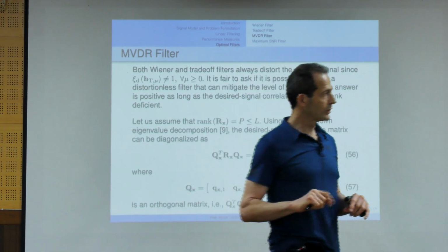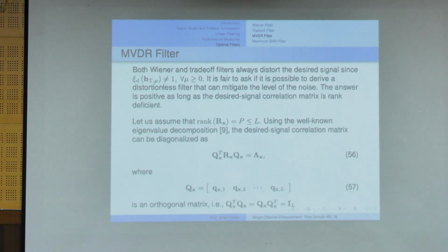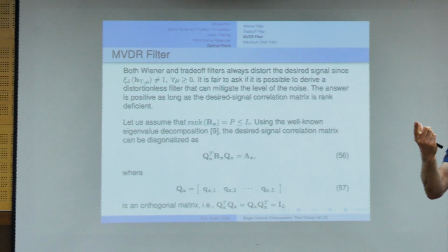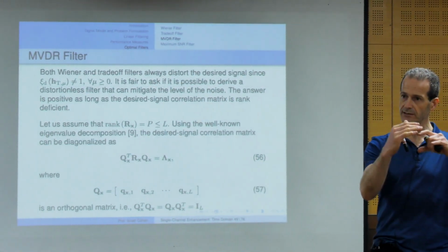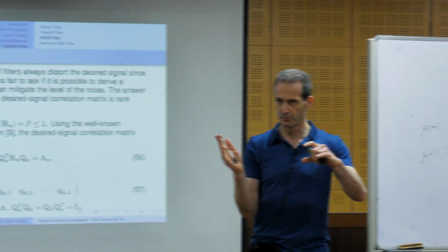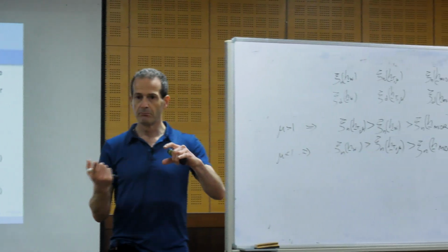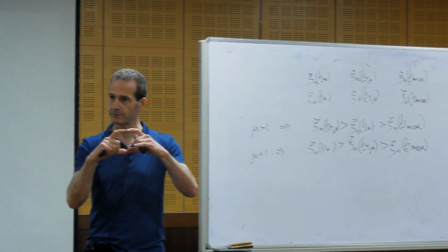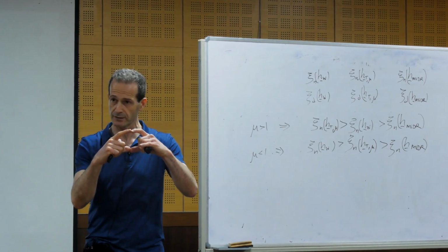Okay. So if we compare it to the Wiener filter, of course, it will remove all the noise in the noise subspace up to 1 kilohertz, and above 2 kilohertz, just like the MVDR. But what will it do in the signal subspace from 1 to 2 kilohertz?